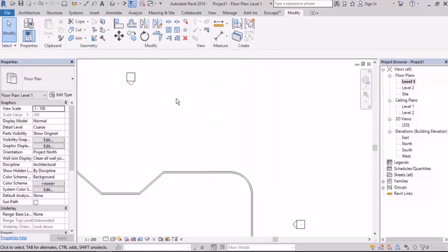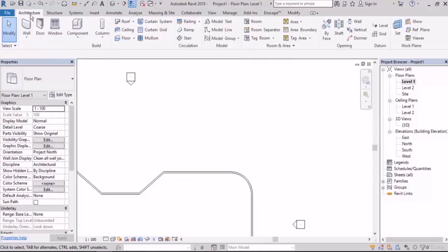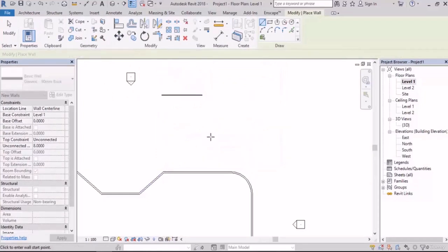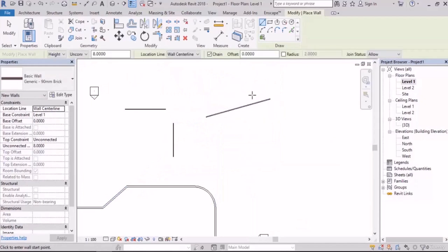And the shortcut is clear, it's TR, trim. But what does it do? Look at the shape of the icon. It creates the corners. It kind of makes you a very perfect corner. For example, we have these two. Whatever our shape is, it gives us a very perfect corner.